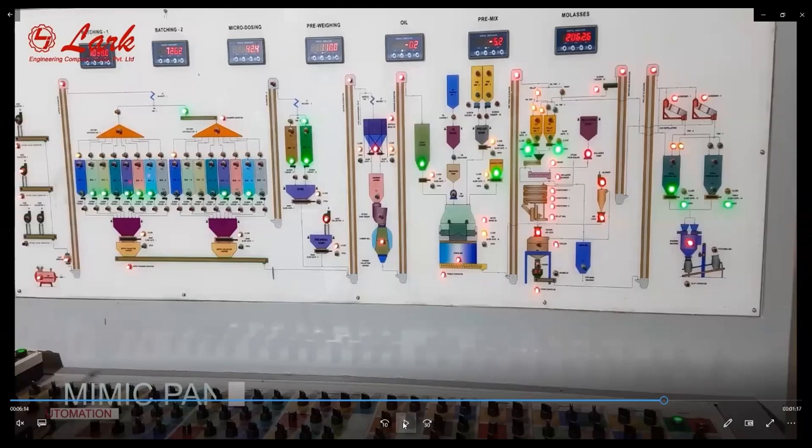He wants to work freely, so he runs the pellet mill at 80-85%, so that he does not have to run around. So in the plant performance analyzer module, you can have an idea of which machine is running at what ampere, at what RPM, at what time. You can have the complete trends in a graph. You can even have an auto generated email at your email ID in the morning at any specified time. In that auto generated email you get the performance of the plant.